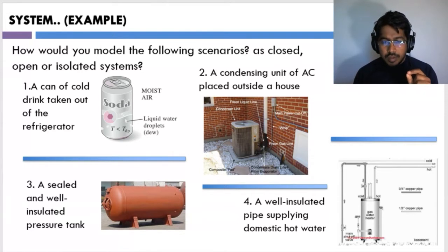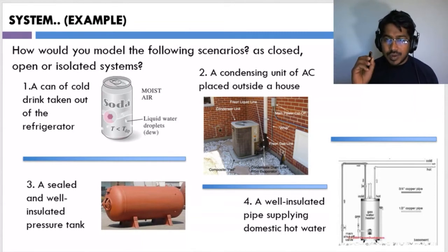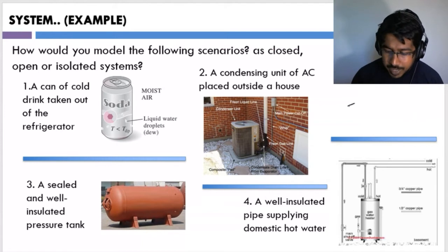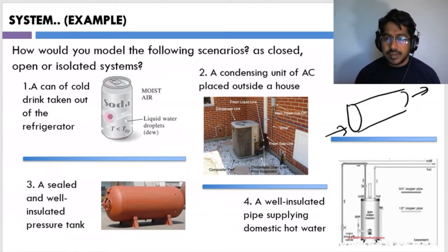The pipe, a pipe section, a well insulated pipe section. So this could be confusing at times. When you say well insulated, you feel okay, now it's insulated, no heat can cross the boundary of the pipe. It's true, but it's important to note the water coming from one end to the other, water can leave, right? If we take a pipe section like this, water enters and leaves continuously, right, when it's under work.